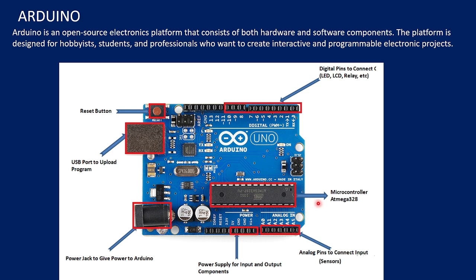and this is a main part which is called the microcontroller, which is ATmega328, and this is the power supply panel where we have two power supplies, 3.3 volt and 5 volt, which you can use to power your secondary circuits, and there are grounds. So 1, 2, there is one more ground here. And the 13 pin is a built-in LED. This LED is connected to 13. For checking purposes we can use this LED,